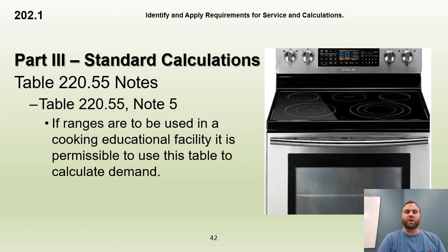And then table 220.55, note number 5. If these ranges are used in an instructional program or a cooking educational facility, cooking school, then it is permissible to use this table to calculate demand for those ranges when sizing the service.